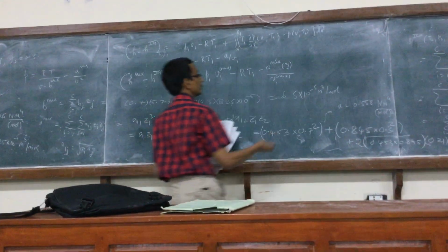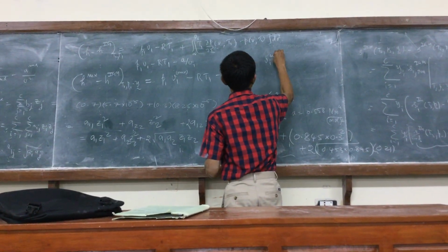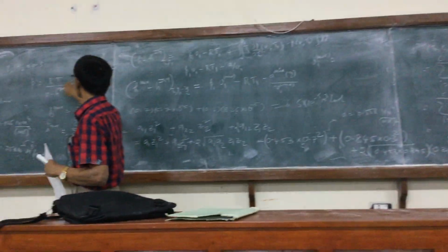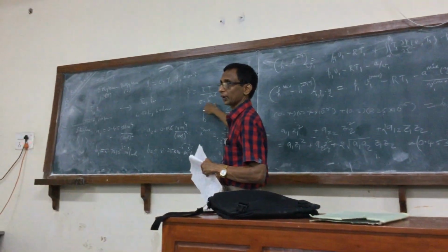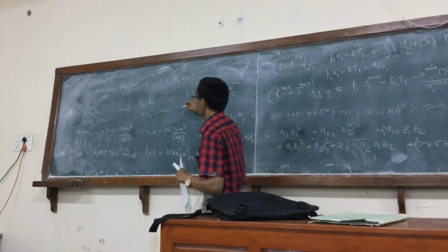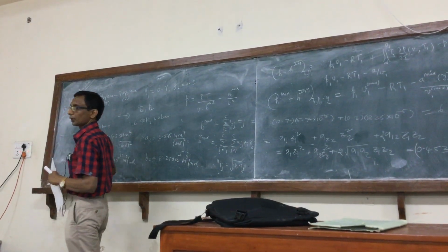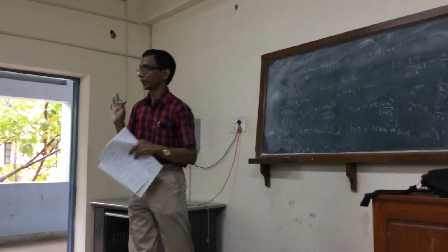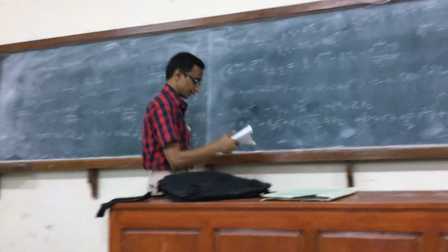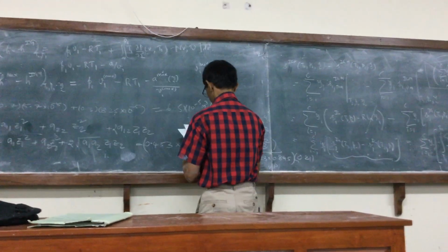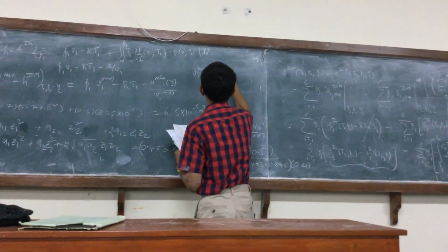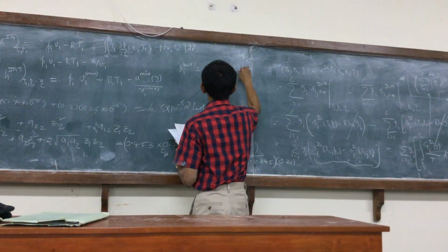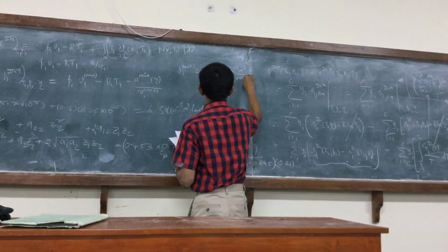The way I calculate V1 mix is to go to the equation of state, substitute these values of A mix and B mix, and calculate V. I know T1 is 323, P1 is 10 bar. So you probably get only one real root, that is my guess. So we take that the real root is 2.537 into 10 power minus 3. So clearly this is indicating a gas state.